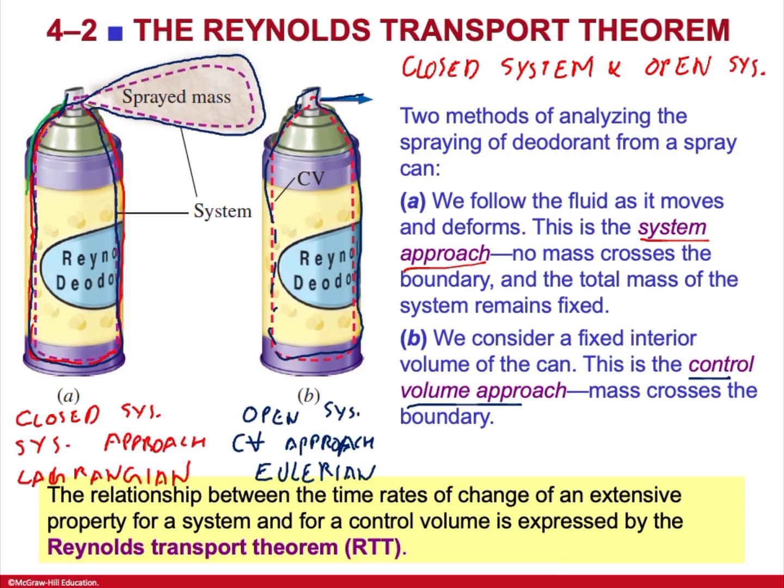So if you spray out, that is fine. You don't need to deform the boundaries. All you need to account for is how much of the mass is leaving the system, or entering the system, and that's it. So this becomes a more convenient approach for a fluid problem, and as a result, for fluid problems, we use this control volume approach.